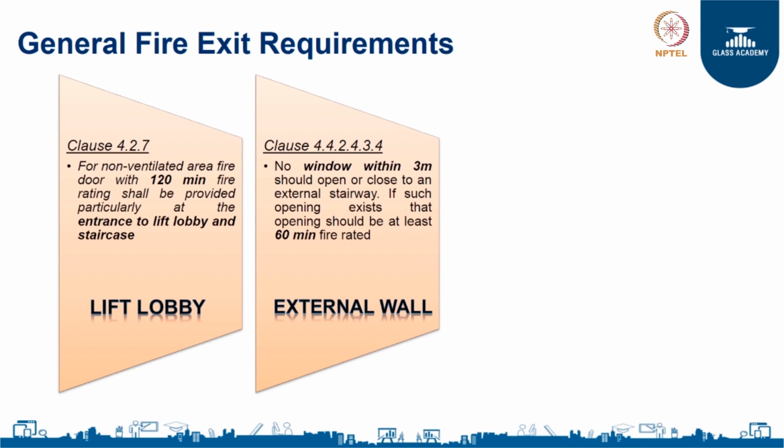For example, if you are going to be using a fire resistant door, the glass is a part of a system that comprises several other parts like the frames, the stiles, the hardware, the fittings, and the gaskets. All of these materials come together to play a role in providing fire protection. That is why it says fire door with 120-minute fire rating, and obviously a fire door with a 120-minute rating will use a fire resistant glass of equivalent or more fire resistance.